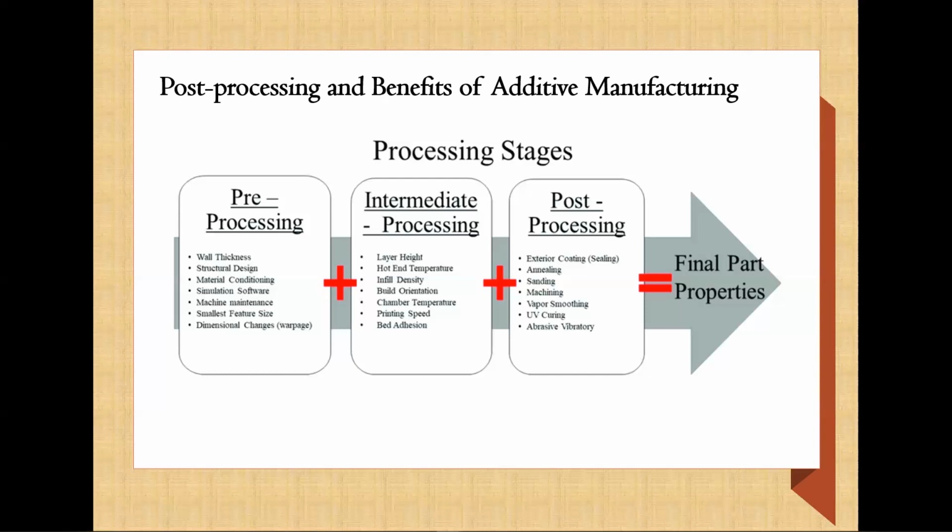However, materials with higher melting points, such as metals like stainless steel, titanium, nickel, etc., can be created in the AM method, typically by powder bed fusion or direct energy deposition, both utilizing powder as the raw material in their processes.